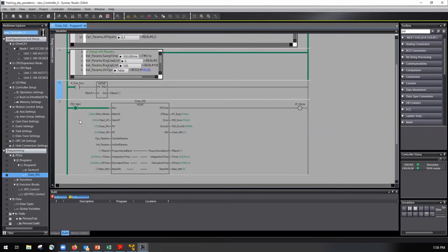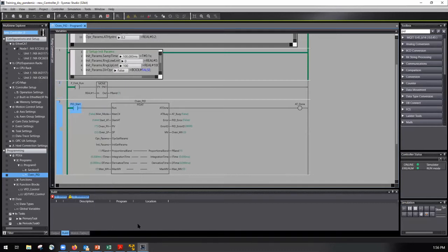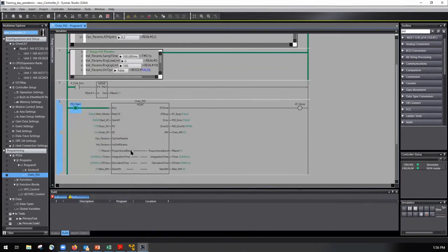Interesting. It should be okay. I mean, you can just turn off your PID block. You can manually write 1 into your p-band, hit enter, and then start your simulator or your PID loop again. And then you can play around a little bit with our variables here, and we still get the same reaction on the output.